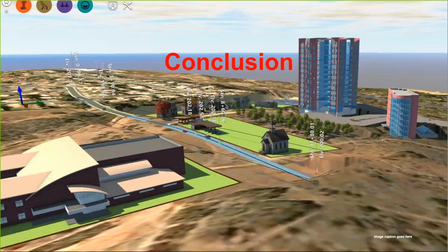Then we brought everything into InfraWorks, and with Model Builder, we generated the preliminary site that had the topology and the existing roads, existing waterways, and the aerial photography from Bing Maps. And then we used that to analyze the terrain with slopes and with directions. Then we brought in our sketches and started populating our concept.